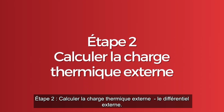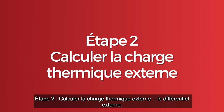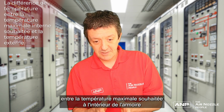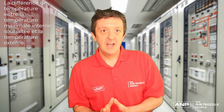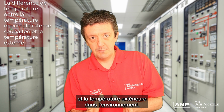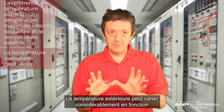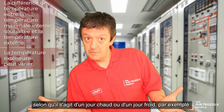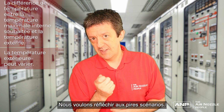Next step, calculate the external heat load, the external differential. This is the temperature difference between the desired maximum temperature inside the cabinet and the external temperature in the environment. The external temperature may vary considerably depending on whether it's a hot day or a cold day, for example. We want to think about worst case scenarios here.